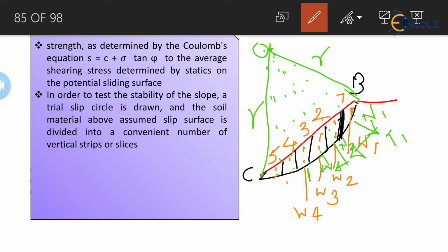So here some friction moment and shearing resistance will occur on that section. The driving moment will be developed and calculated, which gives us T into the radius of that slip circle. The tangential components of a few slices at the base may cause a resisting moment.